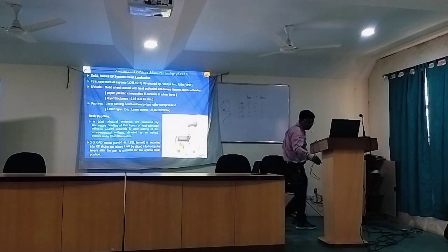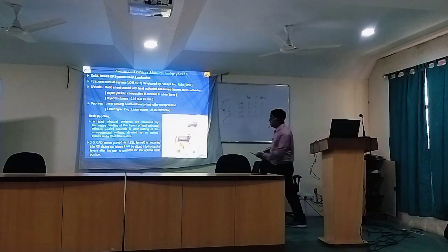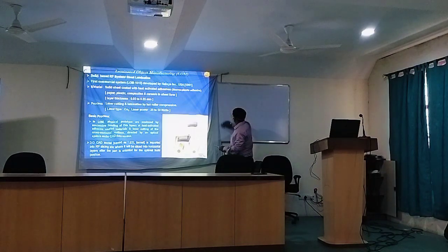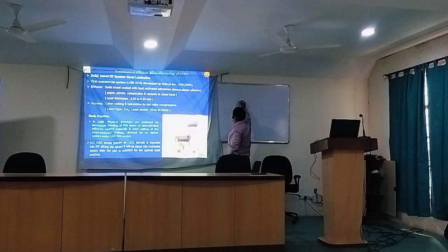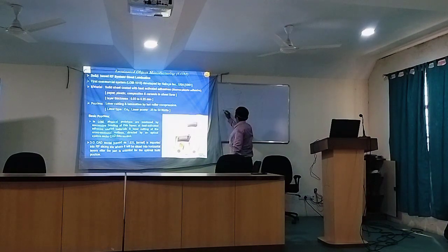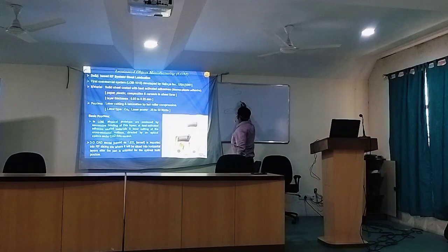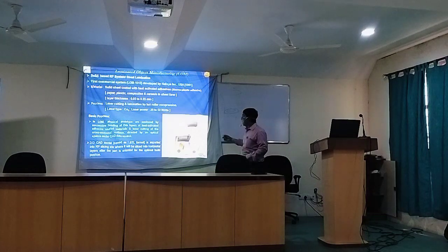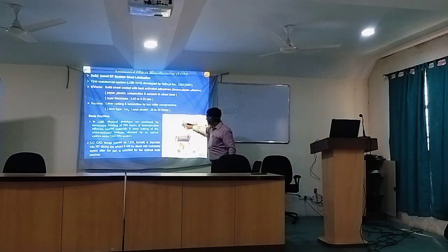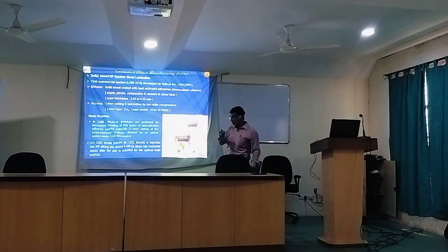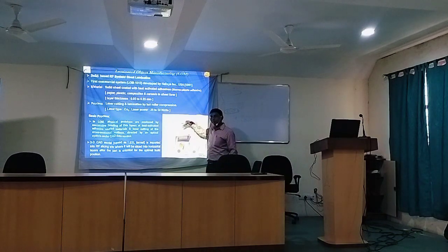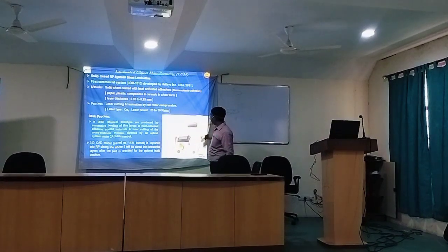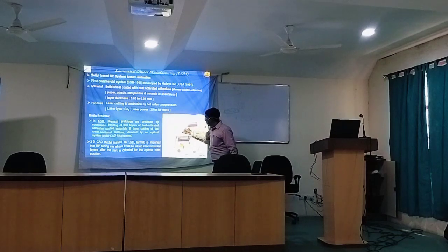Suppose you like to manufacture a component like this, though I have not drawn the engineering drawing, simply representing this. So if your first layer profile is like this, you take the slice data. What you will do? There will be a laser system, a laser source and a laser XY positioning system. It is basically mechanical type XY movement, or it may be optical type movement. It is called the optical laser scanner. So the laser will scan. That means it will control the XY path.